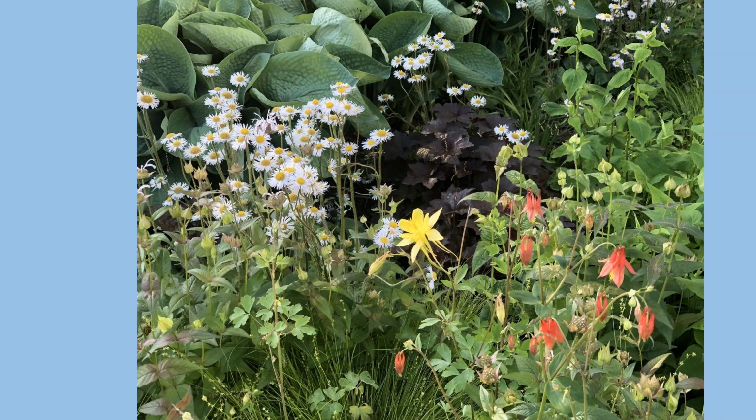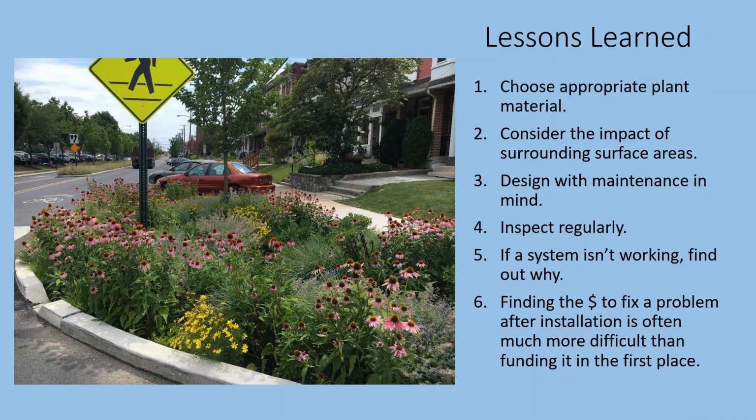So on my last slide, I will just leave you with some of the lessons learned. Basically, it's just selecting the appropriate plant material. And I am an engineer, and I will admit that they did not teach me plants when I went to college. So I cannot work without a landscape architect or someone who knows plants. Making sure that the plants are suited to the bioretention soils that you're specifying is just so vital.